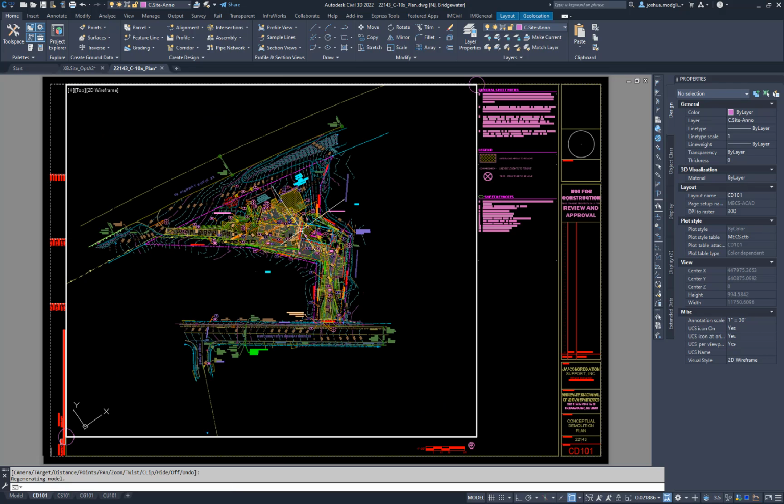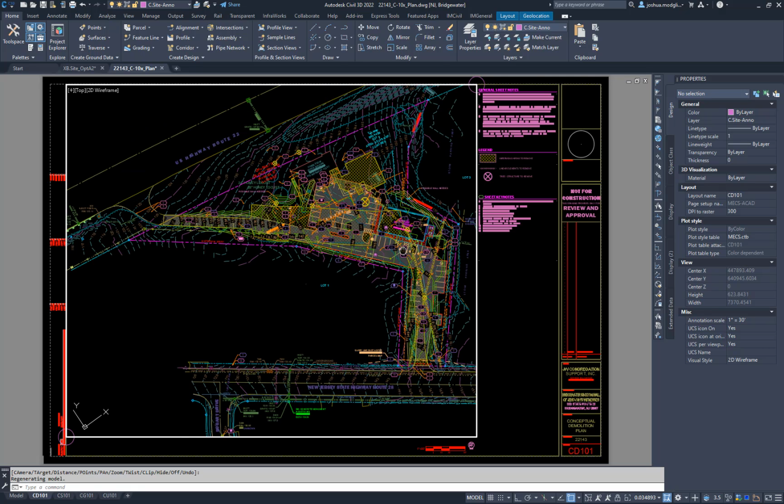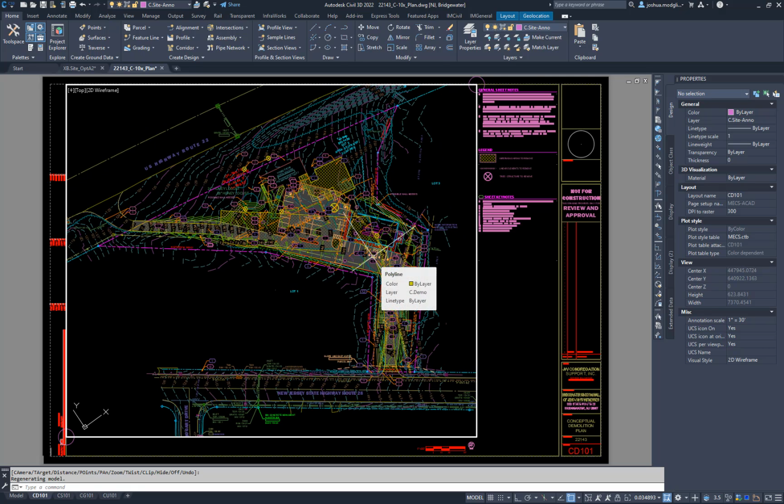Press enter. And you see that it's rotated that view, but that's pretty close to almost lining up with this highway here. And I can fit this information in there, and it looks like it fits pretty well. But you also notice my cursor is rotated because my UCS is still my UCS. It's all good. I haven't changed those coordinates. I've just changed how I've looked at it.